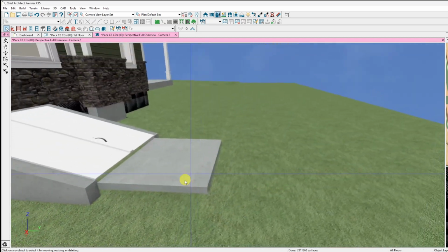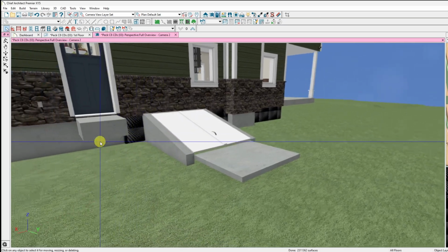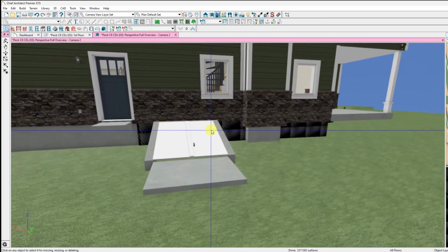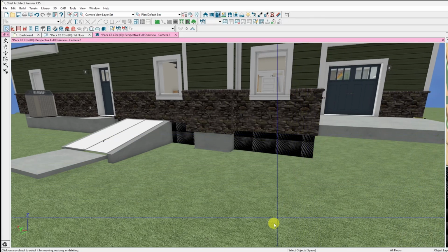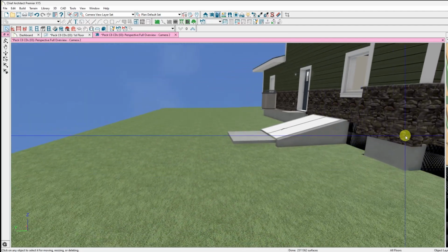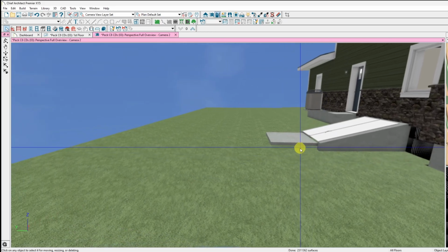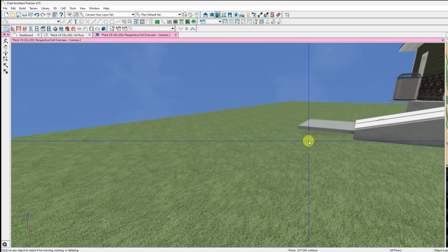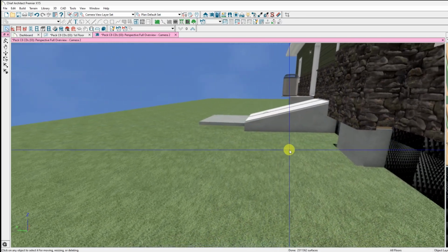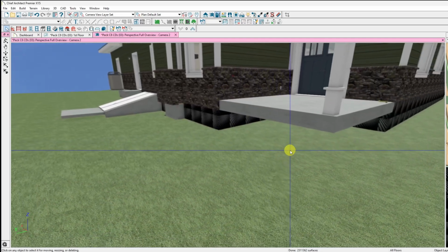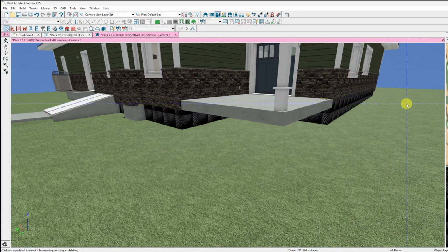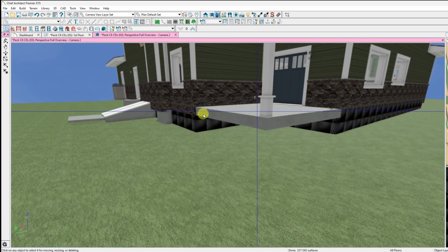So bulkhead door there, and then some sort of pad out here. Whether that gets raised up a little bit or not, I anticipate it probably will come up some, because I've got to get up to a reasonable height over at this back porch, at least to say 10 feet away. So what you see in the AutoCAD drawing was the line drawn 10 feet out, 6 inches down, which is minimal code. So we have to be 6 inches down at 10 feet away and a continuous slope away from the home over that distance. That's a code minimum, and that'll be off any area of the house. So in all directions, it needs to come out 10, down 6, and that's your minimum slope. In a lot of cases, we'll have more than that as we're trying to get out to a certain area, such as the bottom of this bulkhead, or we can raise the bulkhead up a little bit.